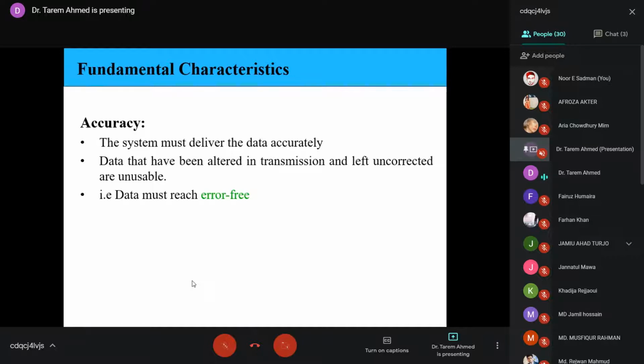Attenuation means signal loss. If you transmit an electrical signal, its amplitude will keep on reducing with the inverse square law. So attenuation is a technical term for loss just due to traversing a distance. Every medium absorbs; an optical fiber actually absorbs a bit of light. So you've sent an optical pulse. If it travels, let's say, a distance from London to New York underneath the Atlantic Ocean, every millimeter the optical fiber will keep on absorbing a little bit of it.